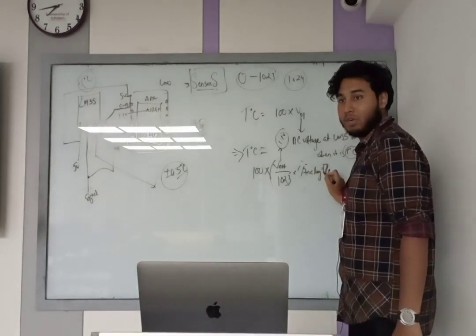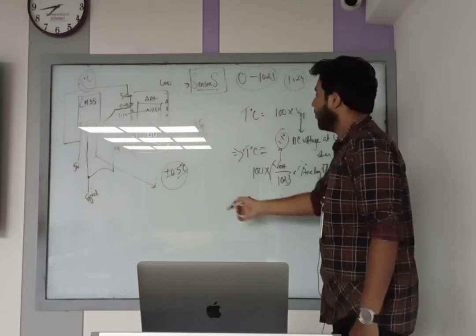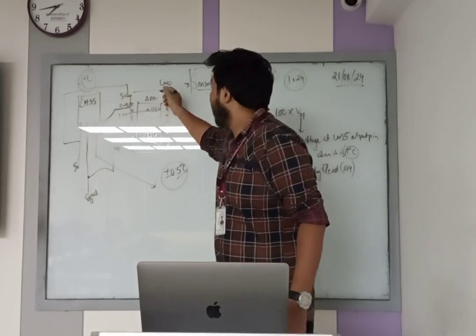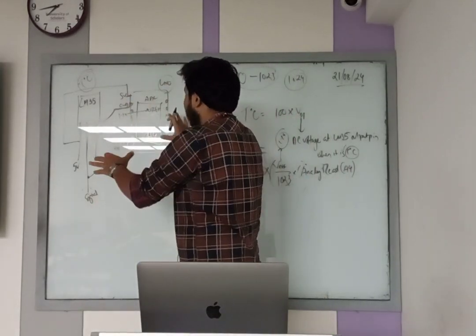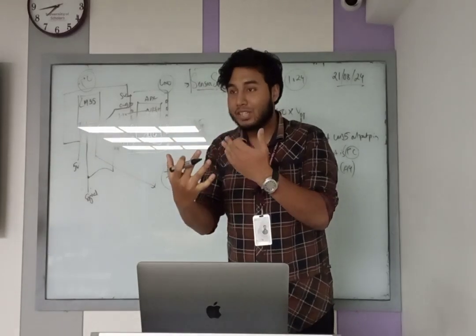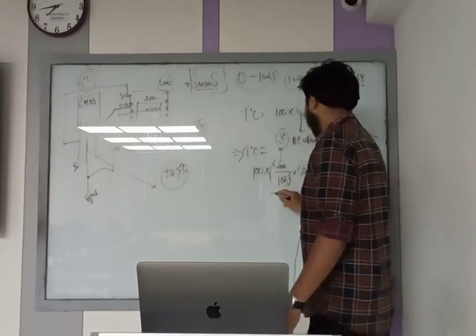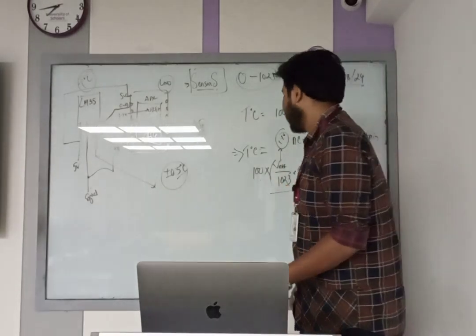So R will be capital. Read A4. Why A4? Because I have plugged the pin at channel number 4, that is, the A4 of Arduino Uno. So I am not going to draw this whole thing. If there is an interaction and a connection over there, draw just this one and write this equation, then you get the full marks. So the question will be something like that.